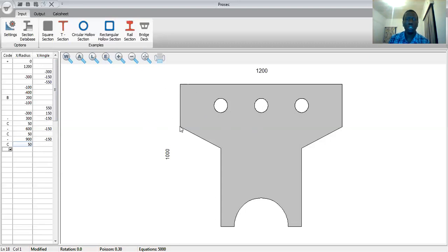Okay, so you work out the points, you work out the starting point based on your global origin, and then you enter those new coordinates. It's quite easy. Okay, so now let's go to the last void. I've got minus again. It's another new void. Starting point is somewhere there. What was that? It's 400, and you've got 300, and I think it's 450. Let's just double check that.